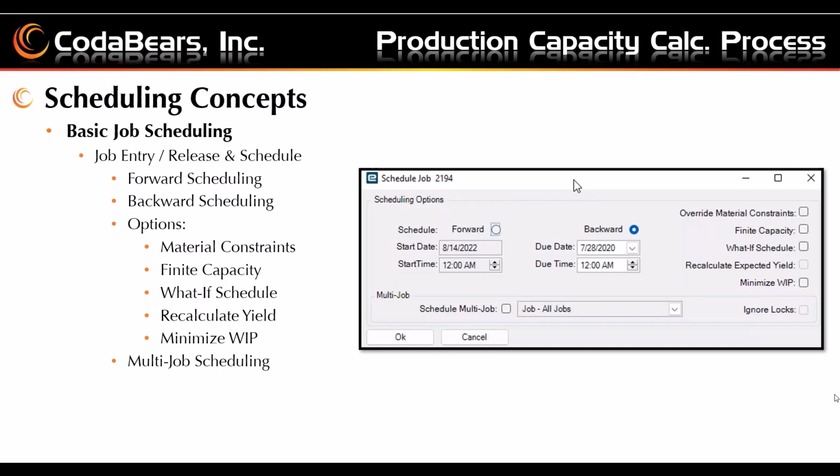Dan Ramirez is saying for global scheduling, it's showing him unfirmed jobs. Is there a setting to only show firm jobs? I would think that you can pull those out just by doing a filter on your scheduling, the column for the job number. Your unfirmed job should be prefixed with MRP or whatever you put for your MRP prefix. I would just add that to a filter there on the global scheduling, the adjust global scheduling order.